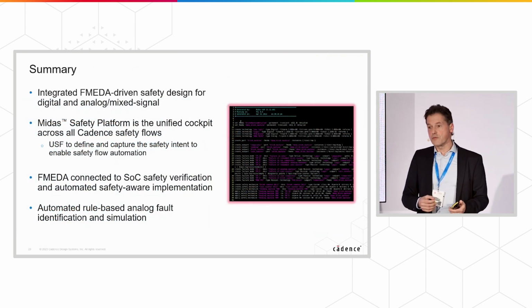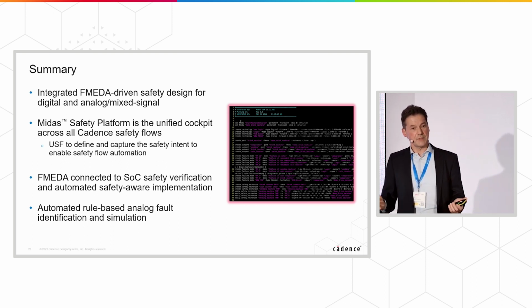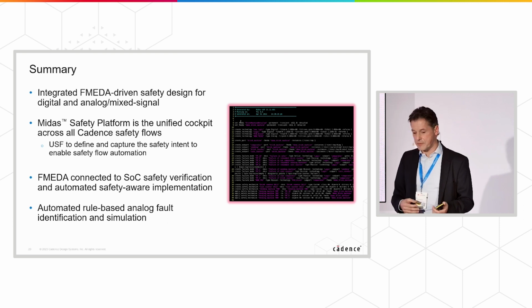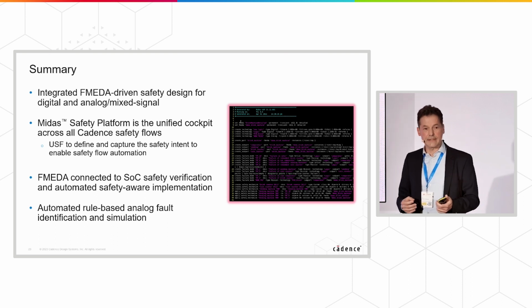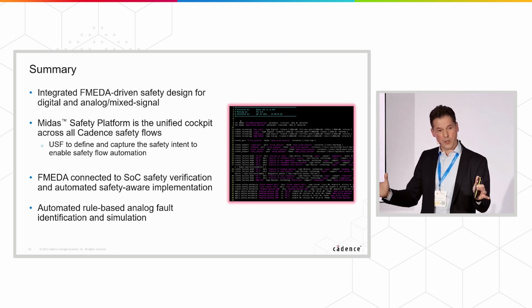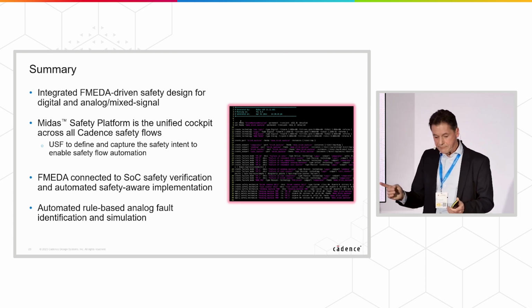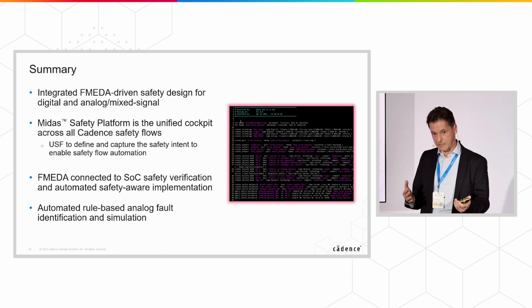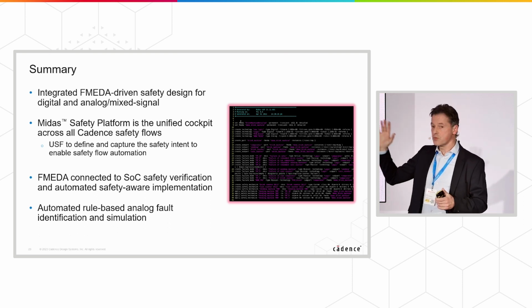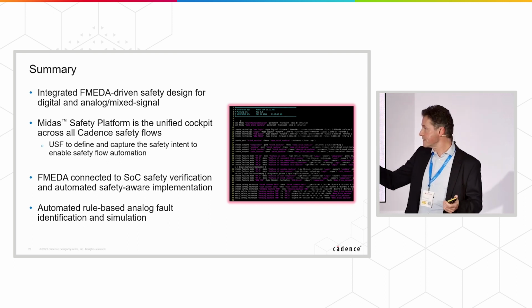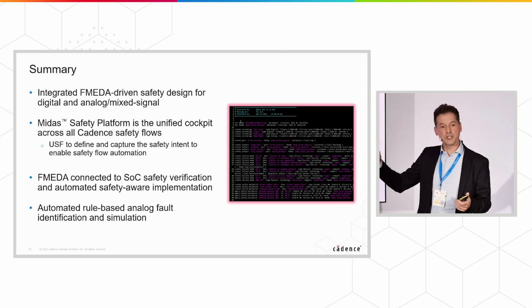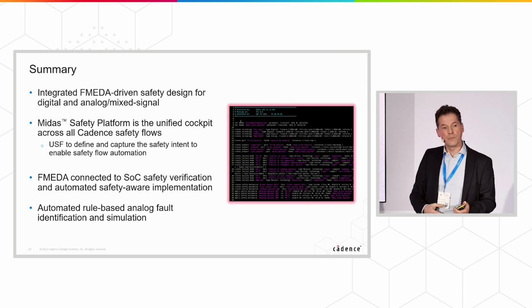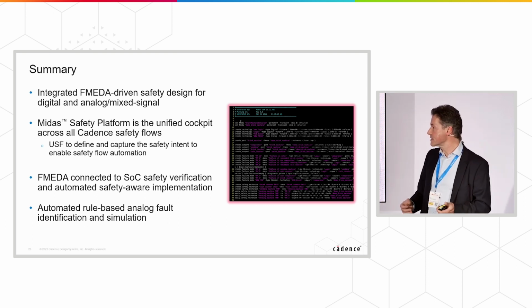So, that brings me to the end of my presentation. With our new safety platform, we provide an FMEDA-driven safety design for digital and analog mixed signal. MIDAS is the unified cockpit that basically is doing all the safety analysis, and USF is the scripting language that allows you to capture the safety intent. FMEDA is connected to our SoC verification flow for an automated safety-aware verification and implementation, and we have also a rule-based analog defect identification and simulation in this flow. And that brings me to the end of my talk.